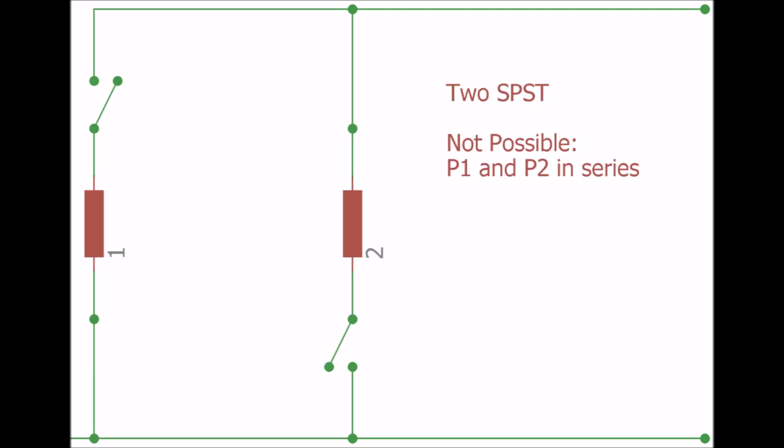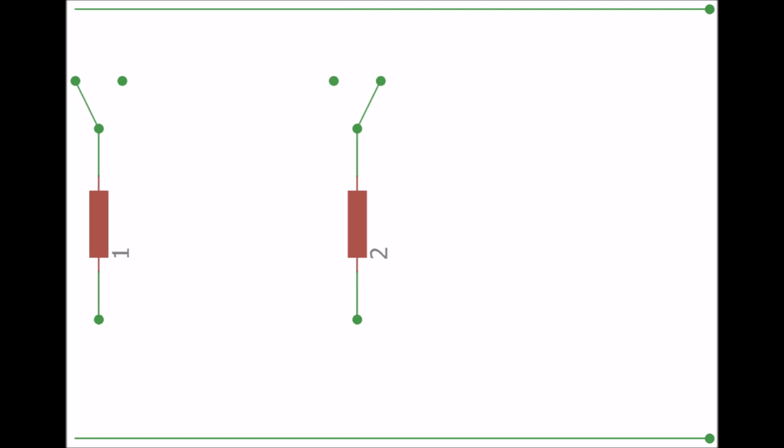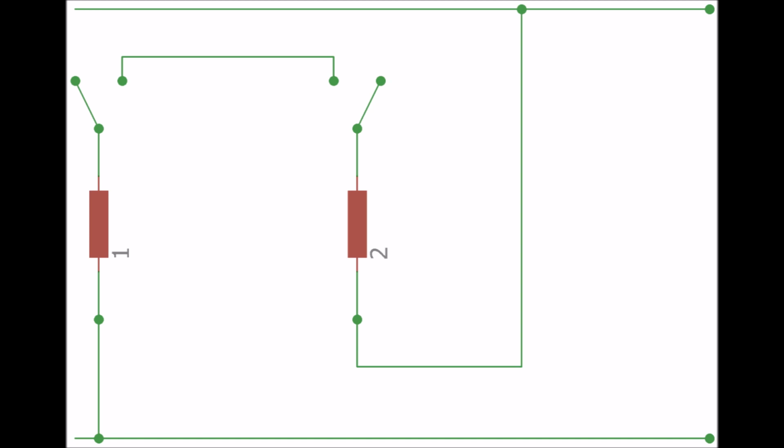Adding a pickup to our setup will also require adding another switch position to the switches, to make both pickups connect in all possible combinations. A two-position switch, or an SPDT switch for each pickup, will be initially used. Paths are laid out to connect the pickups individually, in parallel and in series, beginning with the most complicated. This is quite straightforward with only two pickups. The diagram may need to be rearranged or redrawn for clarity.